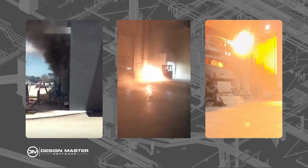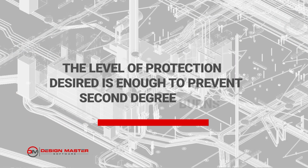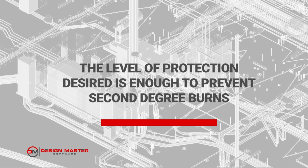You really don't want to ever be in a situation where an arc flash is happening. So there's lots of talk here and in other standards about preventing arc flash, because that's really what you want to do. You don't want to ever be in a situation where this happens. If it does happen, we want to have sufficient gear on to protect the worker in the field. The level of protection from 2002 is the desire to provide enough protection to prevent a second-degree burn in all cases. So it's not to prevent all burns, it's not to prevent first-degree burns, it's to prevent second-degree burns. So some degree of burns is actually acceptable under the calculations and the standards that we're using.